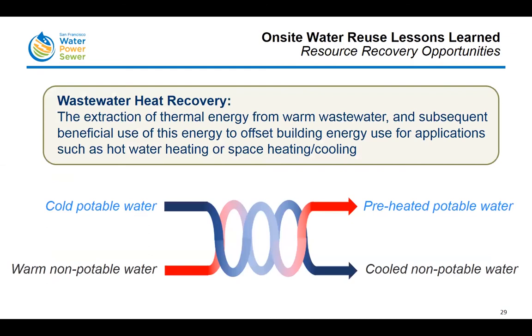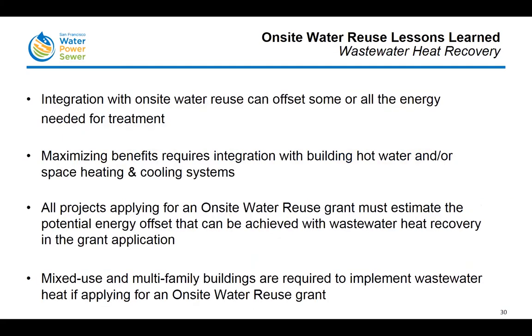Another thing we've learned about and are interested in tackling is the water-energy nexus around these on-site treatment systems. We are very interested in wastewater heat recovery, defined on the slide as the extraction of thermal energy from warm wastewater and subsequent beneficial use of this energy to offset building energy use for applications such as hot water heating or space heating or cooling. These wastewater heat recovery systems can be integrated with on-site reuse to offset some or all of the energy needed for the on-site water treatment.